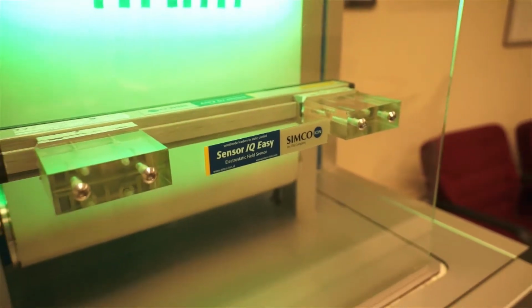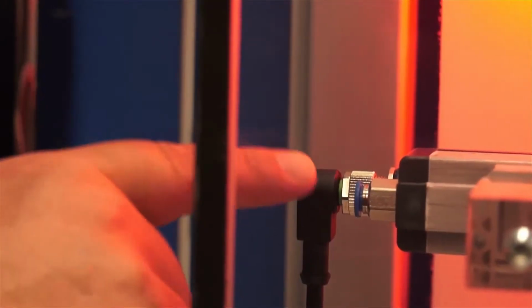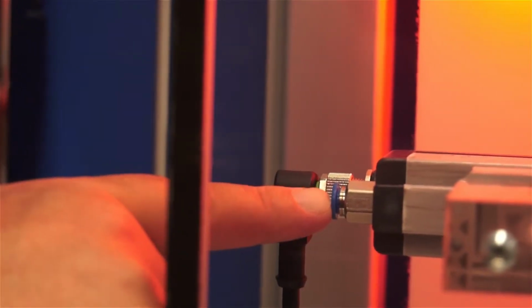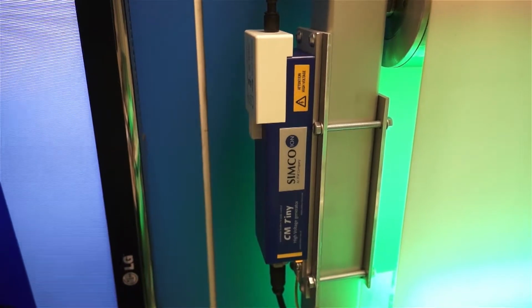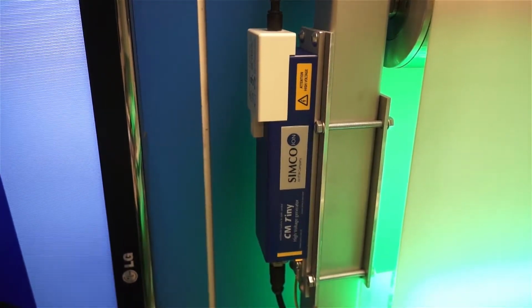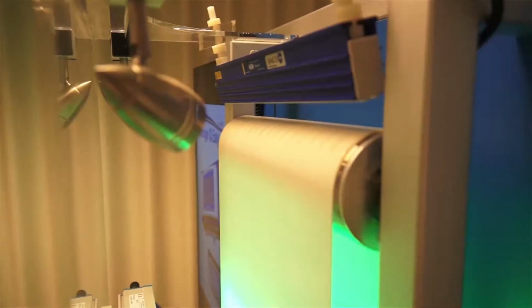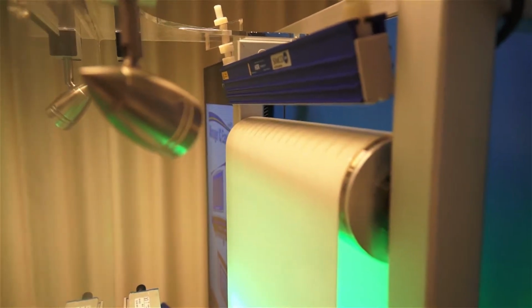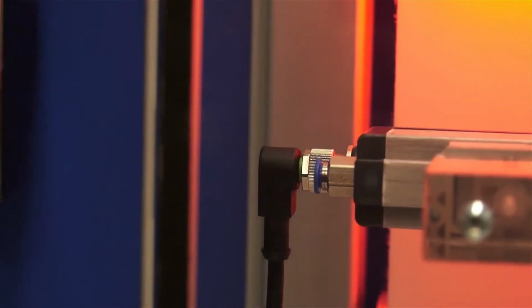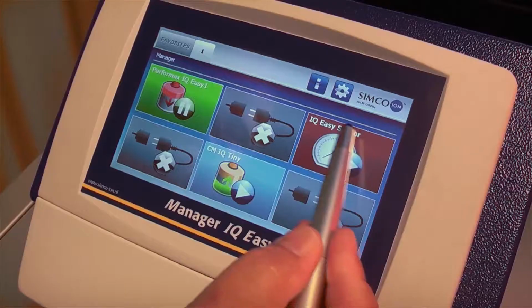Especially in dirty environments, it is recommended to use the air connection and have only a little pressure, lower than 0.5 bars, and it will have a constant airstream through the sensor to keep the sensor clean.